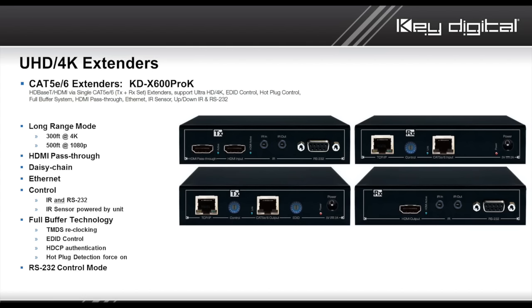By the way, all of these extenders will give you great distance performance. I've been speccing third-party cat wire distance, but if you use KeyDigital's cat wire, KD Cat 6 STP1X is what it's called as a spool, you're going to get some real distance increases. For example, you'd actually get 400 feet 4K and 600 feet 1080p with this product.